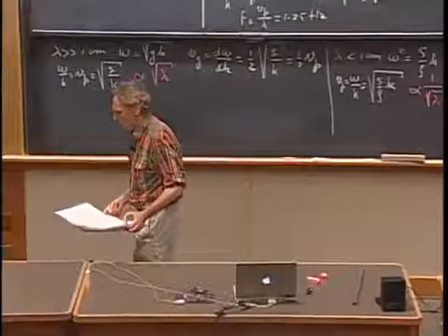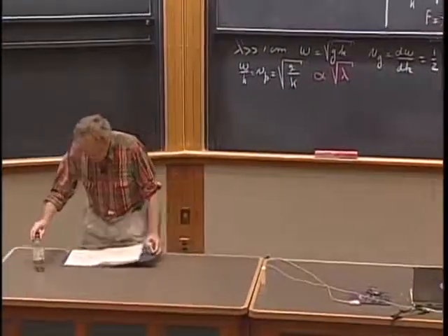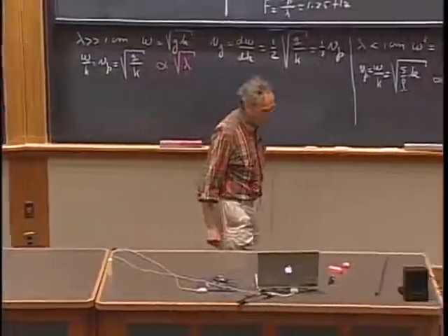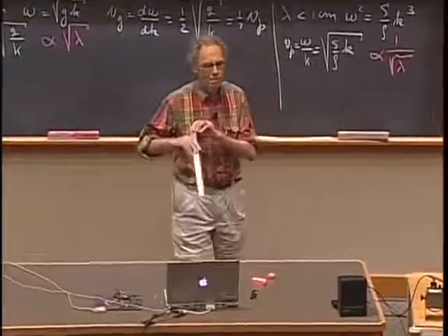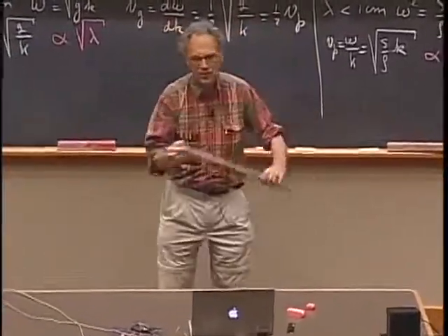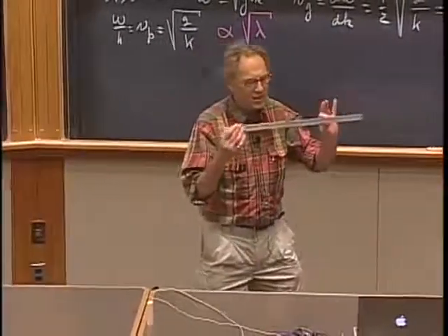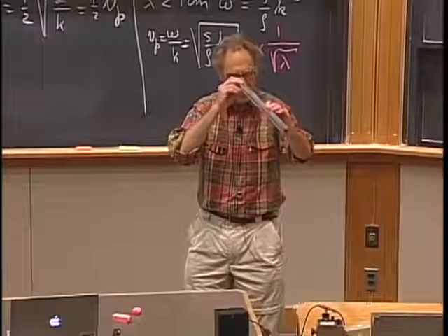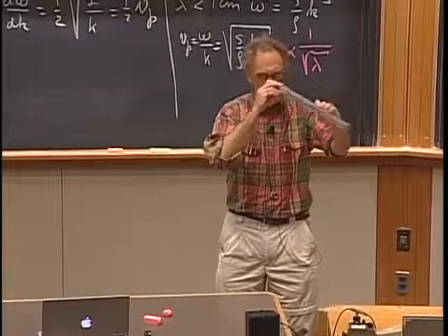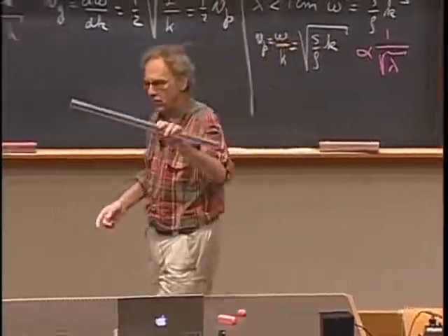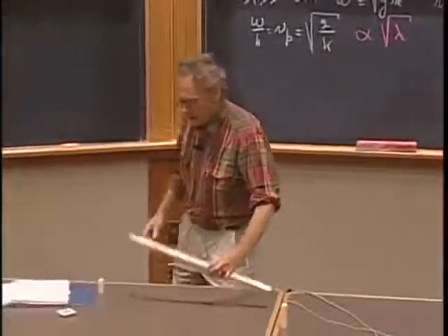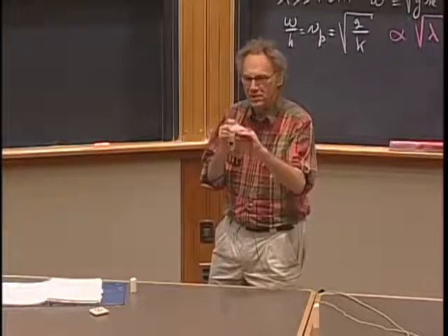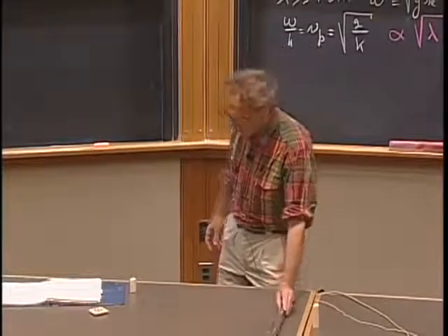We will also explore in 803 the transport of electromagnetic waves through metal pipes. We call them waveguides. Here I have a metal pipe. The opening here is about 1.5 centimeters across. Light has no difficulties getting through. I can look at you, and I can see you. You may be able to see me, I don't know. I have no problems. Light has no difficulty getting through here. But radar, with a wavelength of 3 centimeters, would have great difficulties getting through here.